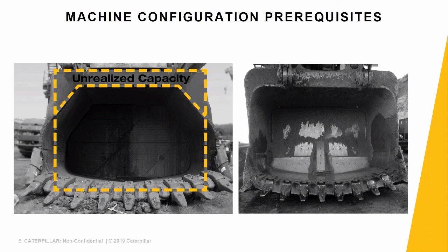And also respawn. When you look at the truck shovel interaction, truck spotting and queue time is probably the single biggest factor that affects the performance of the shovel of all those three. So with the autonomous, the truck is going to get in there quicker, depending on what's going on. Quicker, and as he was saying, the position of it's going to be accurate. So if your crowd position over the truck is from the face having to extend out or come in to be centered over the truck, that increases your cycle time as well. So having that truck in the perfect spot, centered loads every time, you're swinging optimally and getting a faster cycle time out of it. And also you save the lots on that truck. It doesn't need the loader operator to be positioned in the spot.